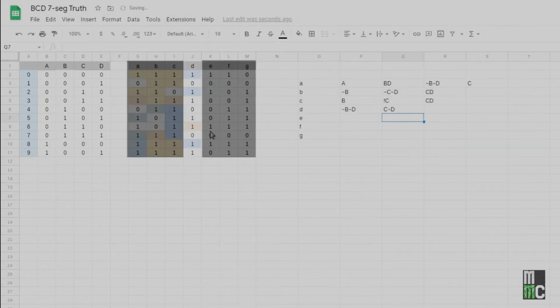And then to get this last one here, we have B is one of the ones we can use, but here's a B where it's off, so we'll have to combine that. But the difference between this one, this is off, and this is on. So is it possible for me to use B and C? So it would be basically not B, not C. That's this one here. Not B and C is on, gets this bit.